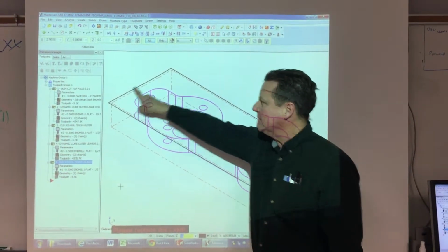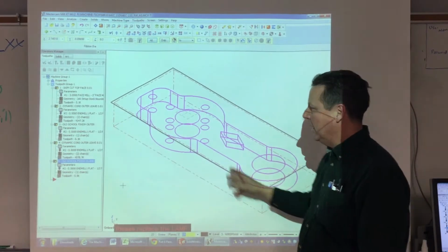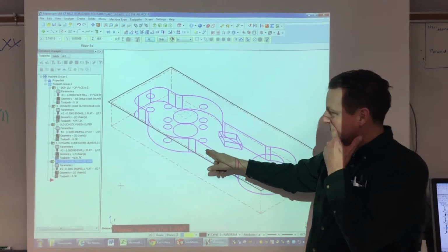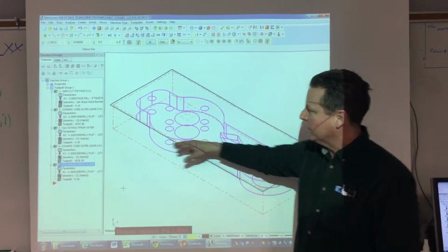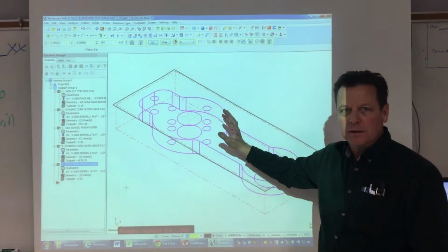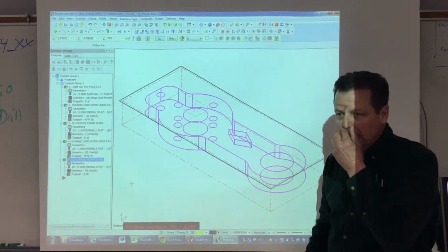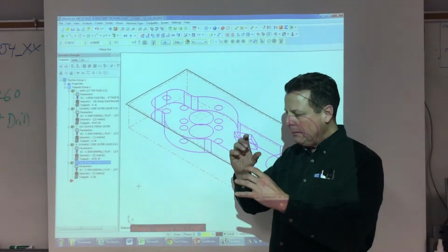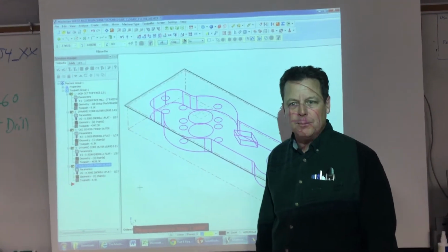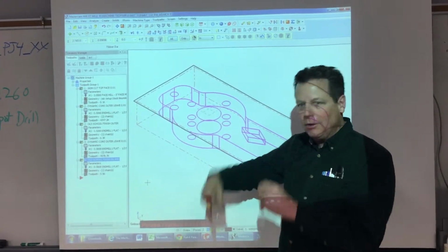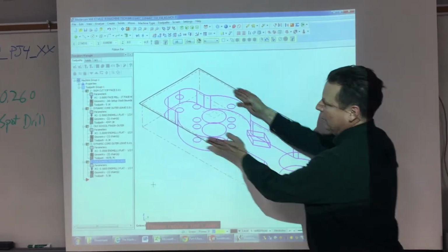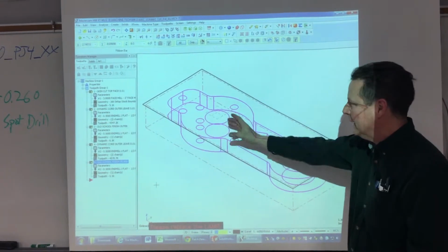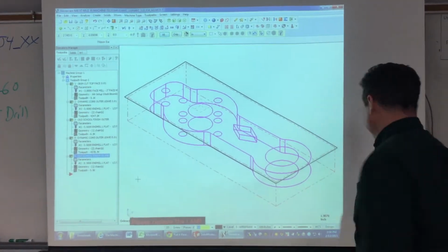So we need to put a fence around where we want to mow, and then we want to chain the boundary of the house so that the tractor doesn't hit the house. Another good way to think about a core is an apple core. An apple core is not a hole going through an apple. It's what's left after you ate all the way around it, right? So that's what we're going to be doing here. We're going to be leaving the core sticking up.